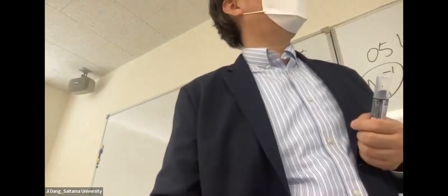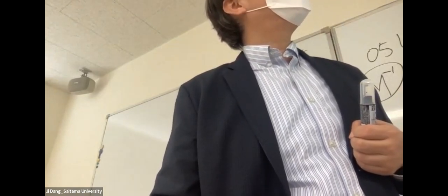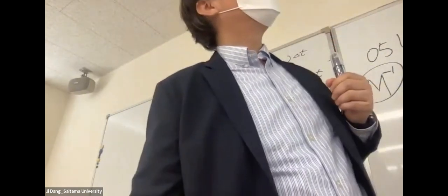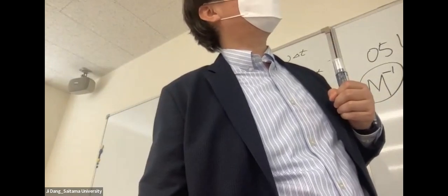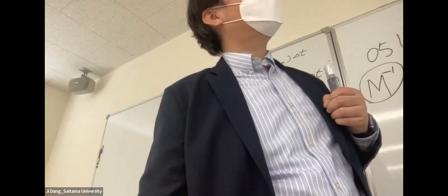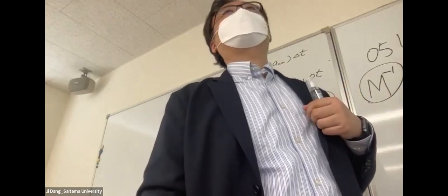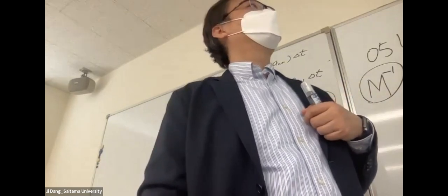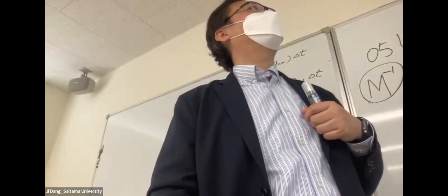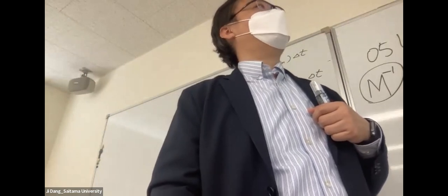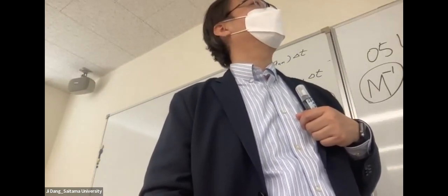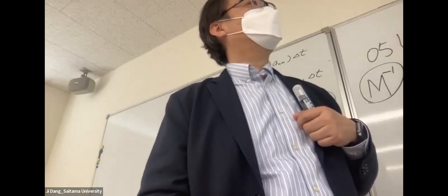Remember that it equals this one divided by this one. And then we put them, remember we have these two equations, right? Vn plus one, Dn plus one. So we need to correct this one and correct this term by this corrector, okay? Also remember that delta Fn plus one is the correct force, accurate incremental force. So we get loading by the bilinear model using predicted displacement. So we get the real force, and then we get the error part of the force, how much error we generated due to the nonlinear force and nonlinear force incremental. And then we calculate the corrector and we correct them by it.